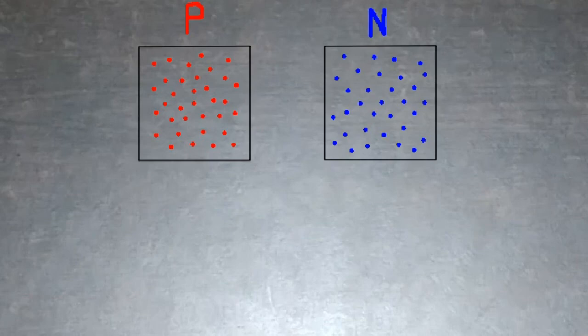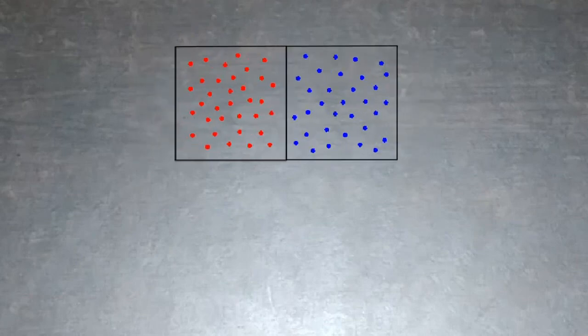The secret to this behavior lies in construction of diode. A diode is made up of two semiconductor blocks. One is p-type semiconductor which have excess of positively charged holes and n-type semiconductor which have excess of negatively charged electrons. When they are diffused, recombination of electron-hole pair takes place which form a depletion layer which has no charged ions.